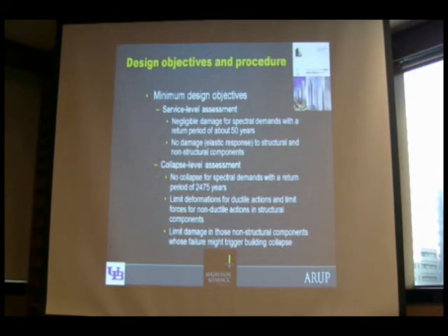So after we had reviewed international practice, we settled on some minimum design objectives for our recommendations, and we required a service level assessment and a collapse level assessment. And the service level assessment really requires no damage in the structural framing system or damage to the non-structural components for earthquake shaking with a return period of the order of 50 years.